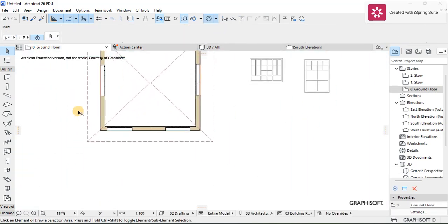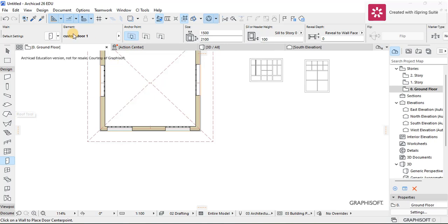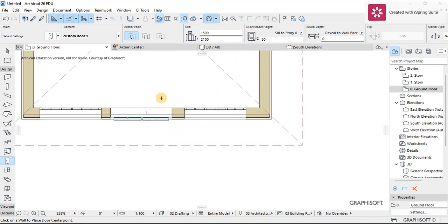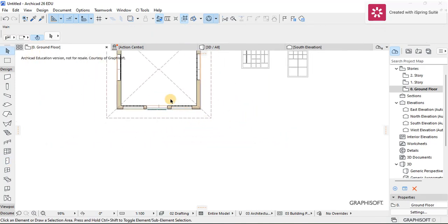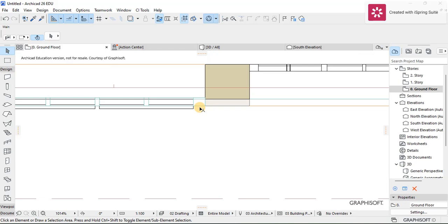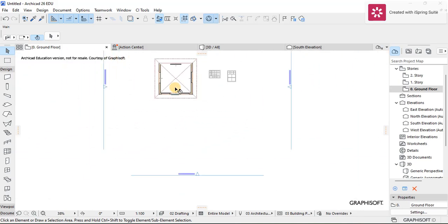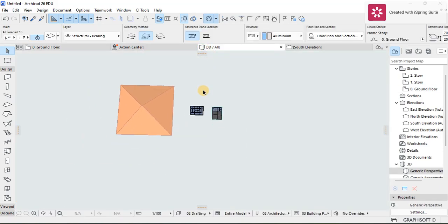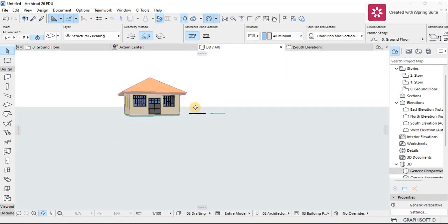and then you're going to the ground floor, and then you're going to now look for the door tool. And coincidentally, our door is on the home page, and then you're going to make the sill to be a bit smaller, maybe 50. And then we are going to place our door here. Yeah, for this door, it's not actually going to swing like the normal ArchiCad doors, but you just have to cope with this. But the custom door is actually mostly necessary when you're making an external door, because ArchiCad does not have metallic doors. So that said, let's see how the windows look.